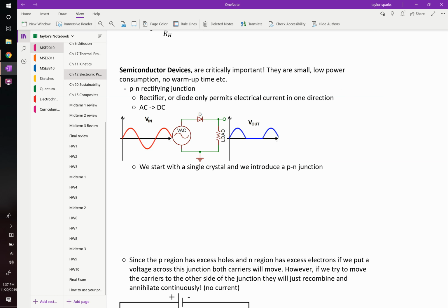How do they work? Well, let's start with just a diode, LEDs, right? LEDs are p-n junctions. If you have an alternating current, this is your voltage, and the voltage is going to produce an alternating current. Take my iron wire demo from the wall, positive and negative, that's switching because the wall is alternating power. It's switching from 120 to 0 to 120 to 0, 60 times a second, 60 hertz. If you don't want your current to be jostling back and forth, but instead you want it to go one direction, which we want in so many devices, like this computer runs off of DC power, direct current power, meaning the current goes one direction.